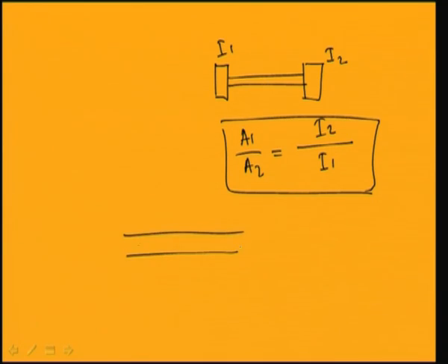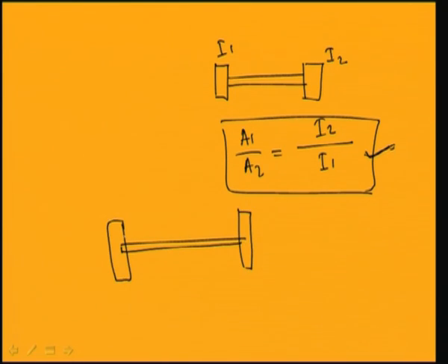Let me find the same relation by another method. So this is the system. In this system, when it is rotating with a frequency, already you know that one frequency equal to 0, the other frequency you have to find. We have given that the rod has a length L, and when it is rotating with the other frequency, there will be a node point here. This node point means this point will have no vibration.